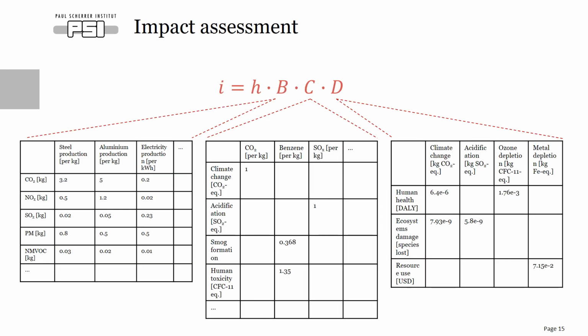And this will output 1 vehicle kilometer as a transport activity. Once we have computed the material and energy inventory, we obtain a list of materials and energy associated to 1 vehicle kilometer for all the vehicles we are considering. However, this list as is not very useful because it is hard to interpret and to make the choice of a technology or vehicle type over another one. To do so, we can multiply this inventory by a matrix that contains emission factors per units of products of material and energy. The product of this multiplication will give us how much of each emission is emitted per vehicle kilometer for the different vehicles.